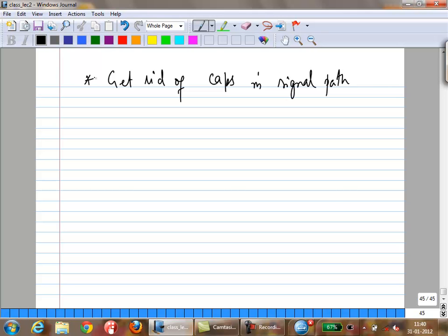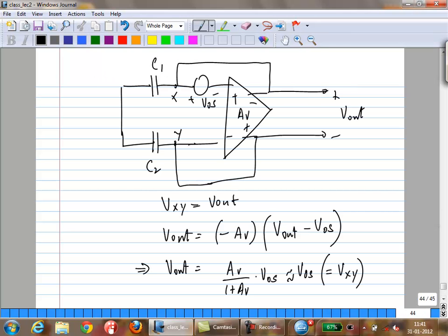So the way to do that is, we are going to use an auxiliary amplifier, so a second amplifier, and that is going to have capacitors where we are going to store this offset. Those capacitors will be for offset cancellation. Okay, I mean offset measurement. In this case, you're doing offset measurement.